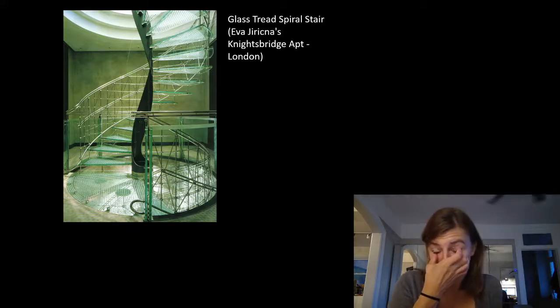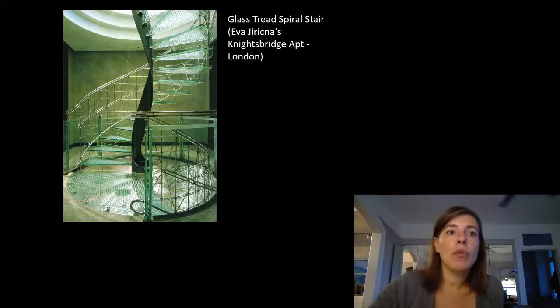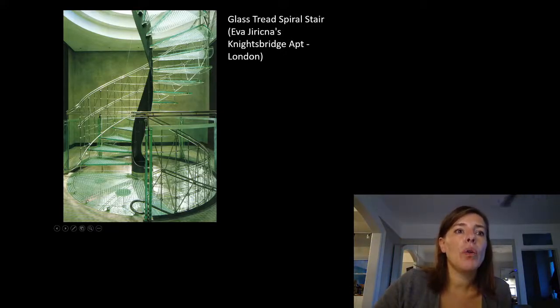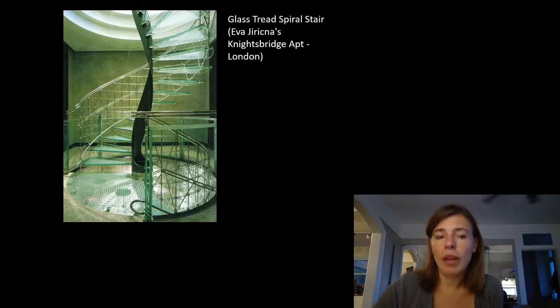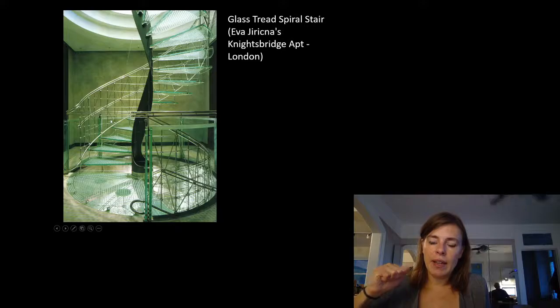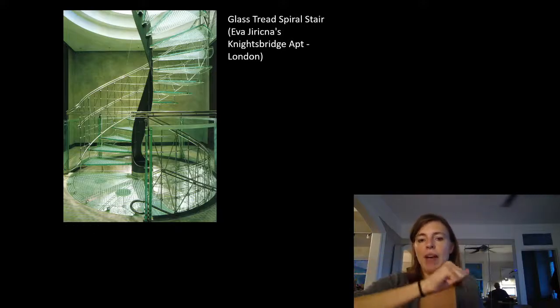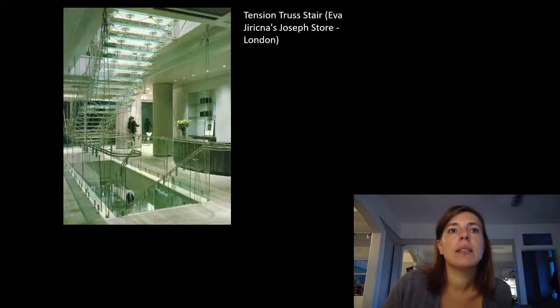So remember I talked about why it might matter the outward force versus the inward force. This guard would have been analyzed assuming elements were only in tension. So when they're in compression, they're not working for us, and when they're in tension, they are, because they're such thin elements. And so you might be able to make your elements smaller by having lower forces for the inward pull instead of the outward pull.